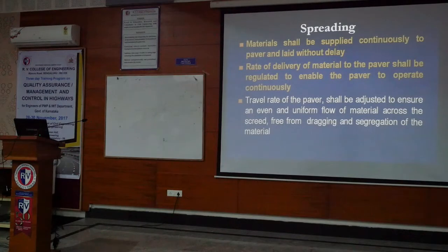Construction, when it comes to the paving, everything should be synchronized. In the sense, the speed of the paver should be adjusted to ensure even and uniform flow of material across the screed. That's one. Next, the rate of delivery of material to the paver also has to be synchronized. I am paving here.